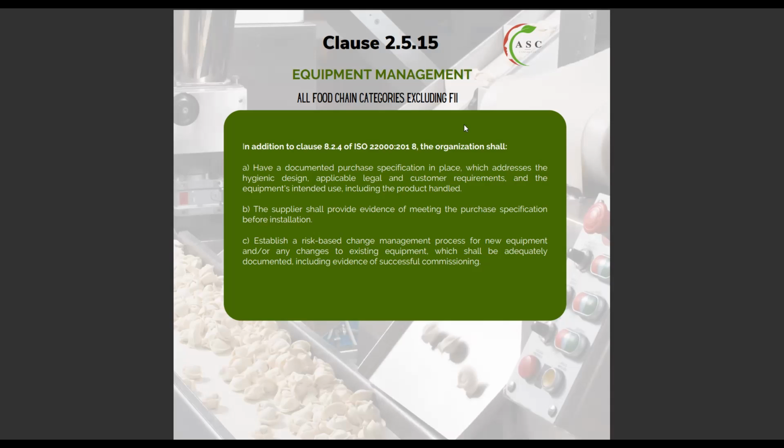The first thing that the organization shall do is to have a documented purchase specification in place, which addresses hygienic design, applicable legal and customer requirements, and the intended use of the equipment, including the product handled. The supplier should also provide evidence of meeting their purchase specification prior to installation. So it's a document that you create that has this checklist, and the supplier must prove that they have been made aware or indeed they comply with that specific requirement.